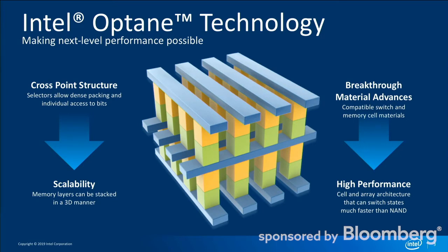So the very first thing that Intel came out with was an SSD, right? In comparing it to the existing NAND SSDs in the marketplace, there were some remarkable differences with the Optane SSD. One of the things was that because this technology is bit addressable, the Optane drive doesn't suffer from write amplification, right? Every time we write to a NAND device, there's background activity that needs to take place to sort of sequence the write and get rid of the old block. In Optane world, you change the bits right on the media.